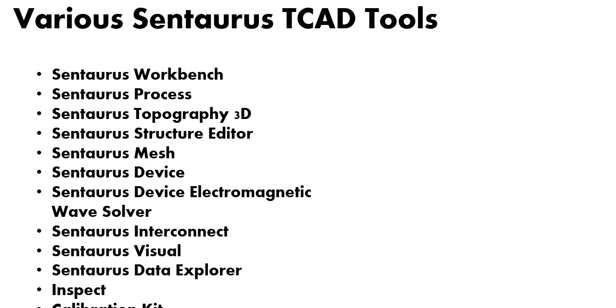Sentaurus Process is used for the fabrication, Sentaurus Topography is used for the issues and integration of fabrication with the device, Sentaurus Structure Editor creates the device geometry, and Sentaurus Mesh. Now Sentaurus Mesh basically meshes the structure editor geometry, which creates the boundary conditions with the finite element structure.